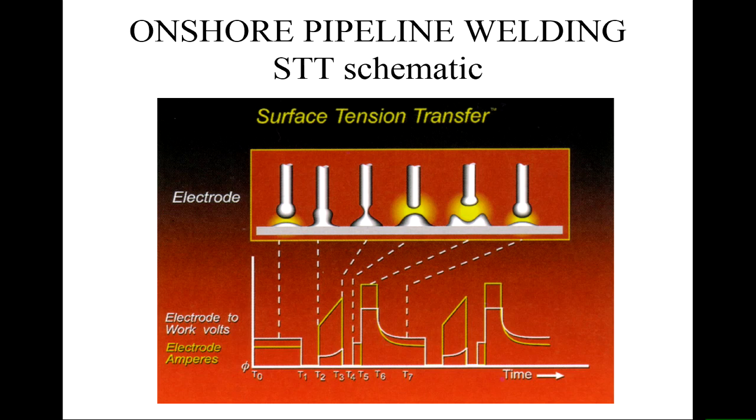And at time t1, you effectively switch off the arc, and the wire is driven forward, and so the wire then comes into contact with the surface. When the wire comes into contact with the surface, current can flow, because it's metal contact. The current goes right up and increases very rapidly, because the resistance goes up as the temperature goes up. And the voltage then goes up slower to match that. So effectively you have something in contact.